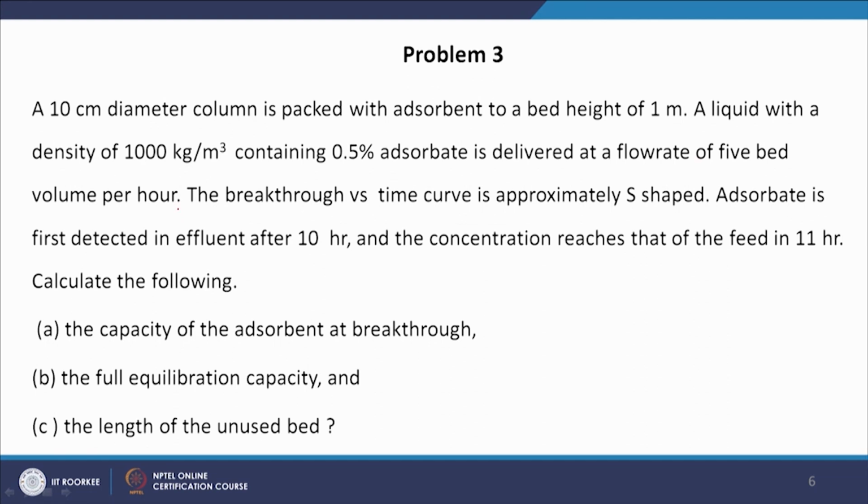The breakthrough versus time curve is approximately S shaped. Adsorbate is first detected in effluent after 10 hours and the concentration reaches that of the feed in 11 hours. Calculate the following: the capacity of the adsorbent at breakthrough, the full equilibrium capacity and the length of the unused bed. So, this is again a problem of adsorption in a packed bed column.